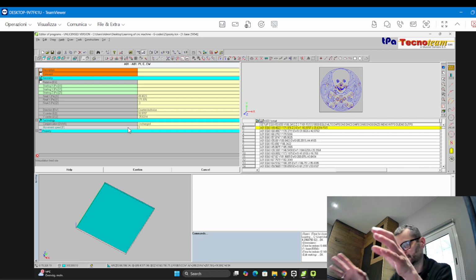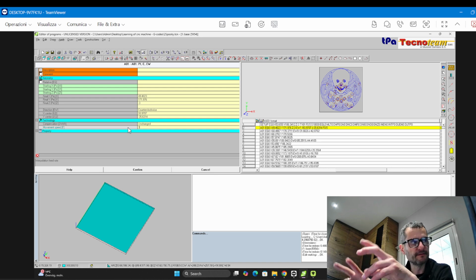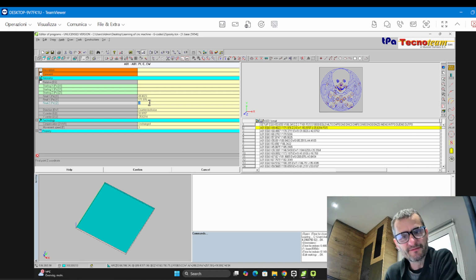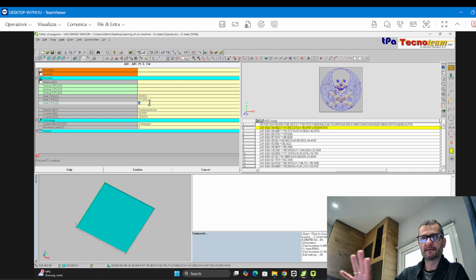But of course, you don't have to modify the parameter for every line. You come back in AlphaCam, you change it one time, and then you create a new CNC for the machine, and that will be okay. When you save this TCN file from AlphaCam, you put it in the machine. In the machine, you just save like this, so it overwrites itself.